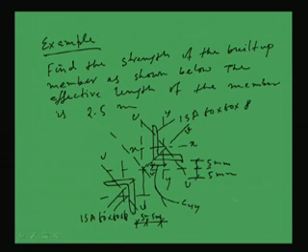So, what we have to calculate is the radius of gyration for calculating the strength, that is in x direction as a whole, in y direction as a whole, about major axis, about minor axis. So, in 4 directions we have to find out the radius of gyration and consider the minimum one for the calculation of the strength, because the permissible stress will be calculated on the basis of minimum radius of gyration or maximum slenderness ratio.